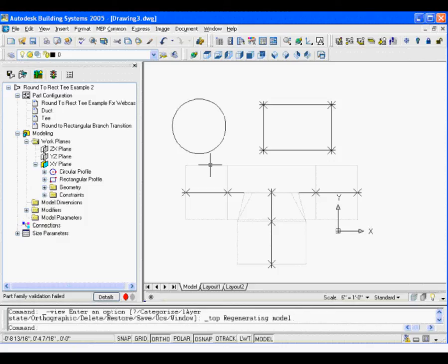If you're going to do it parametrically, it needs to have additional information than what the standard object gives you. So this is going to do a little bit more than what a general AutoCAD solid can do for you. A lot of that is behind the scenes, so it gets a little complicated when you think about it. Best rule of thumb is just stay inside the Content Builder environment to truly build the parts. Anything else? I think that's it for now.